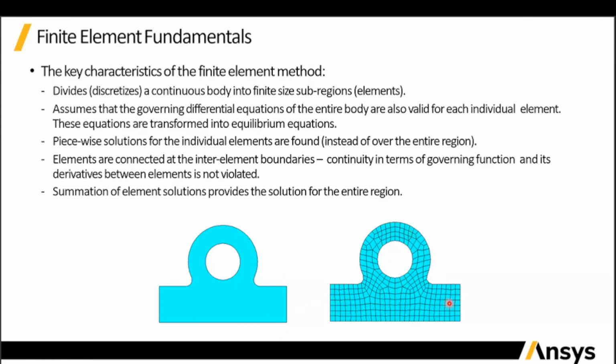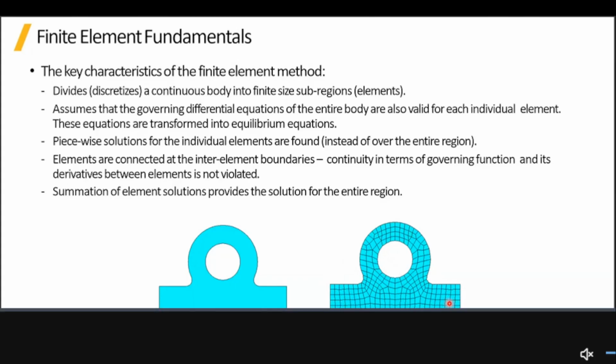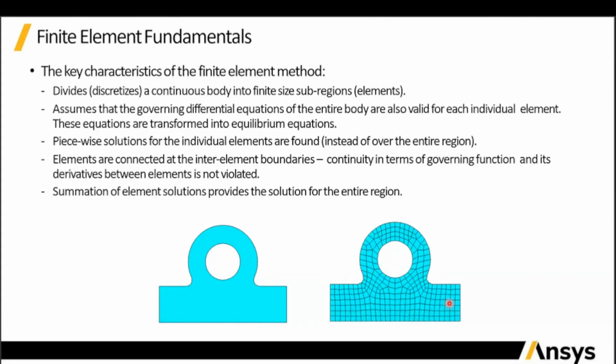This FEM, that is the finite element method, assumes that the governing differential equations of the entire body are also valid for each individual element, and then these equations are transformed into the equilibrium equations. So this method first solves the individual elements.